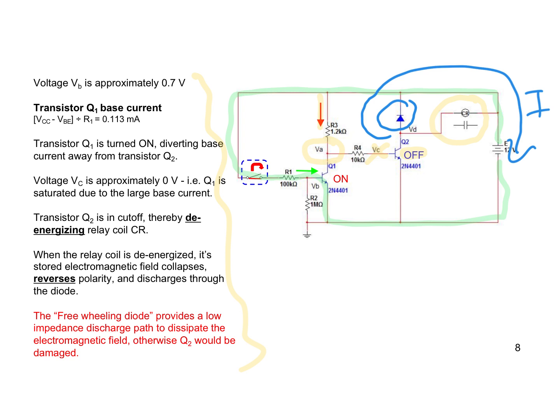If we were to leave that diode off, what would surely happen is that high discharge voltage would destroy the collector junction of Q2. So this is a common feature whenever using any type of transistor to control anything electromagnetic, solenoid or relay or whatever, to protect that transistor. And again, that's typically called a freewheeling or a snubber diode.